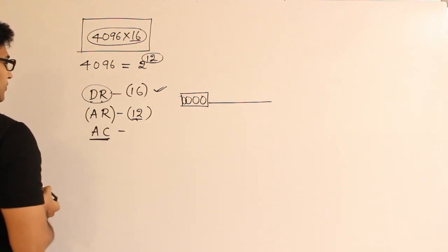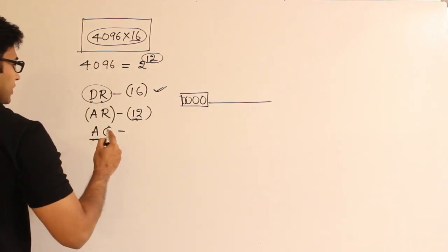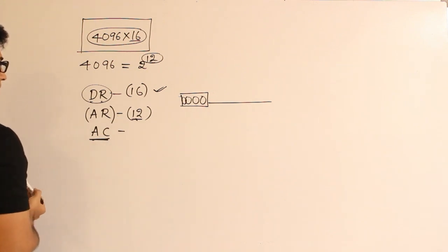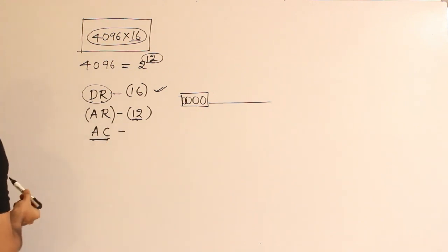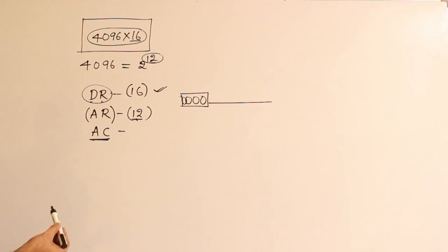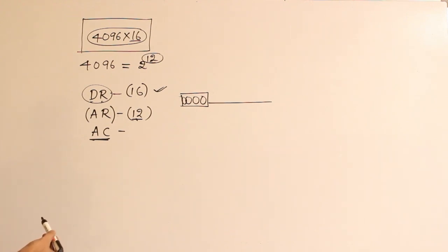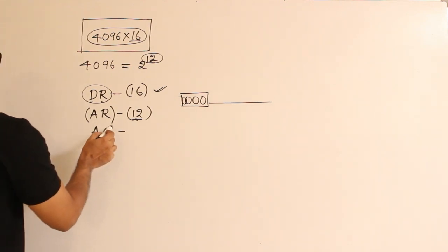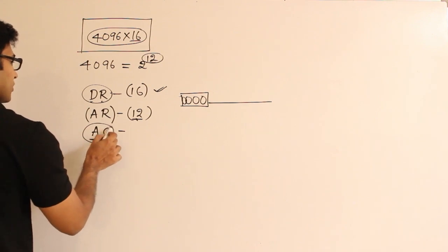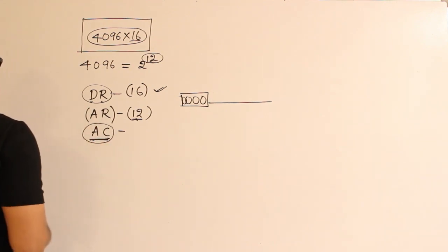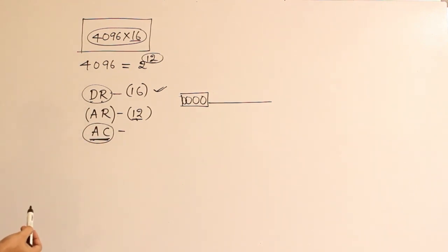The reason is that the ALU will not be connecting to the bus directly. Therefore, if you have to transmit the result of an operation from the ALU to the bus, we are going to transmit it to the accumulator, and from the accumulator we are going to transmit it to the bus. Got it? So anyway, when I show how the accumulator and the ALU are connected to the bus, you will understand their actual operation.